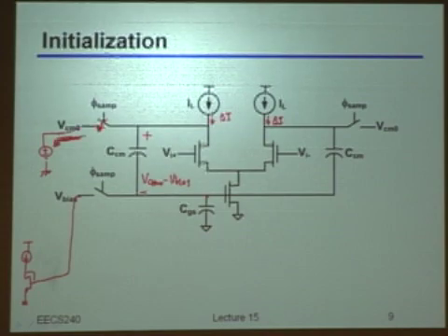Now, if there is a relevant amount of resistance there, you might have some glitches, or you might have some movement in the common mode that you didn't want. So you should keep this resistance very small, which implies that most probably you need to spend power for that. Why? Because most probably you will have your band gap or your reference circuit, and it's just not enough to create your VCM0, and so you will need to buffer it, right?